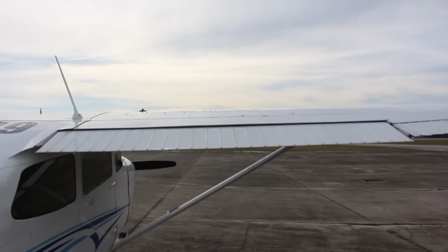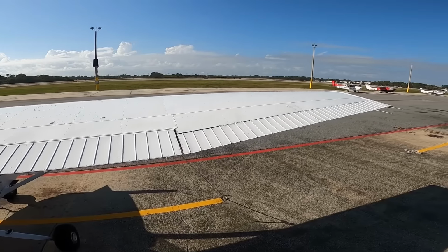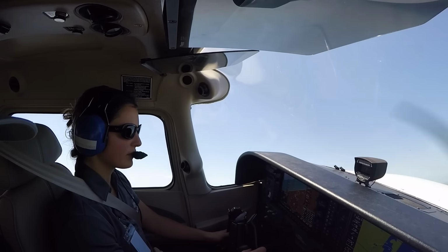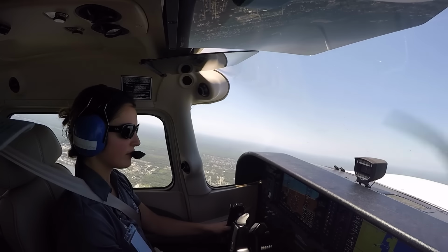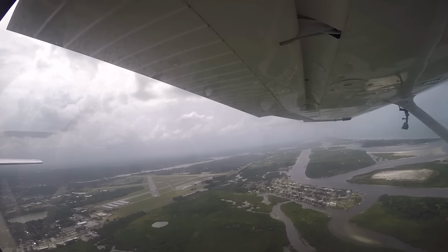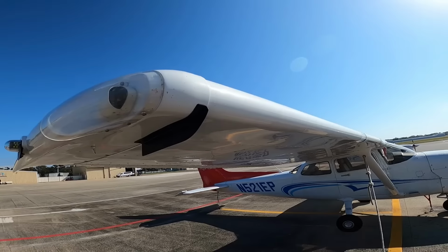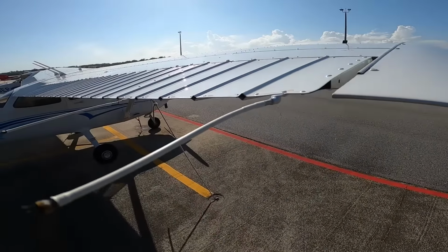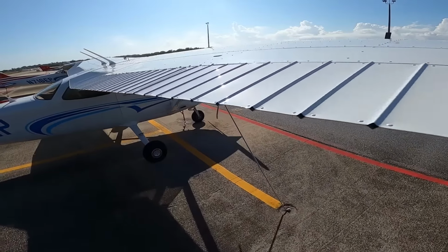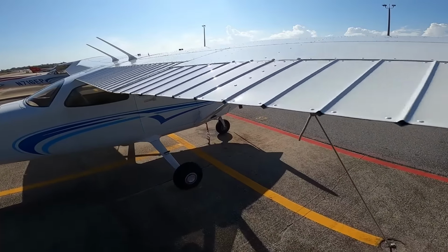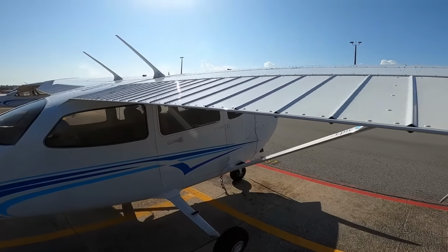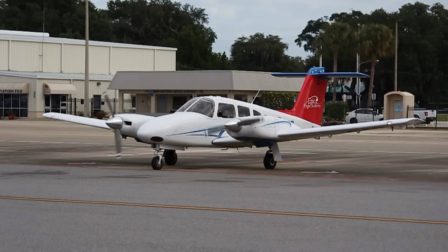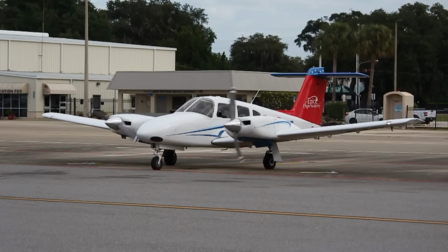Wings include ailerons and flaps. Aileron is another French word meaning little wing or fin. They are used in pairs to control the airplane's roll or bank. Flaps reduce the stalling speed of a wing at a given weight. The leading edge of the wing faces the front of the plane. Likewise, the trailing edge of the wing can be defined as the back edge that includes the aileron and trim tab. Some wings are fixed high on the plane above the fuselage, known as a high-wing aircraft. Low-wing aircraft are planes in which the wings are installed lower than halfway up the fuselage.